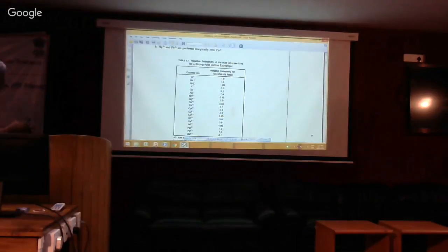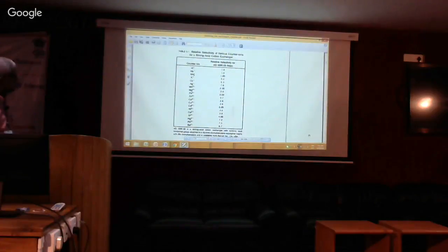That's all I'm trying to say for cation removal. But if you are looking at its selectivity, let's see. So these selectivities are always based in terms of hydrogen. So this is all relative, as you can see. So hydrogen is always 1. As compared to hydrogen, sodium is 1.5. Well, you can see, 1.5 is not very different from 1.